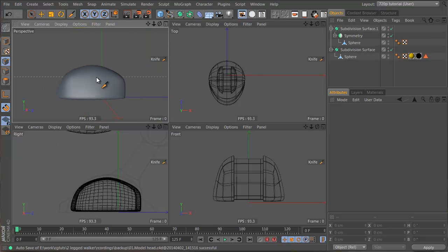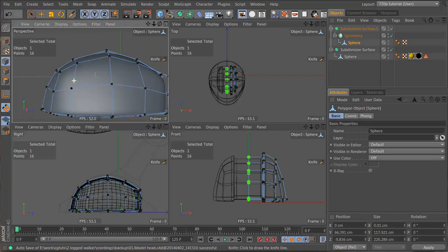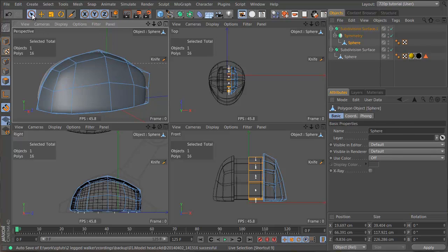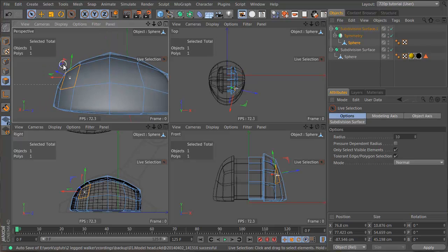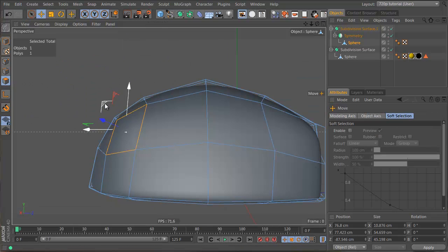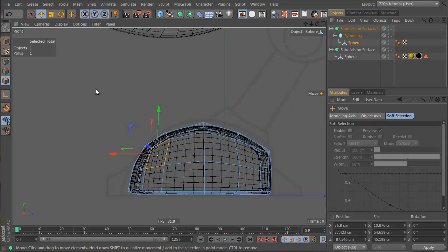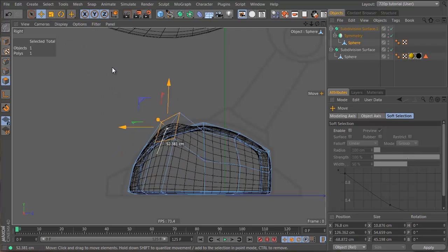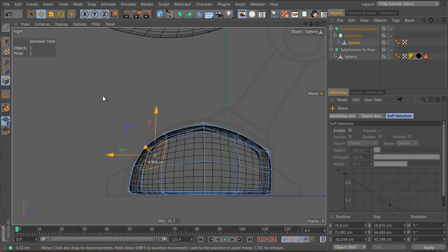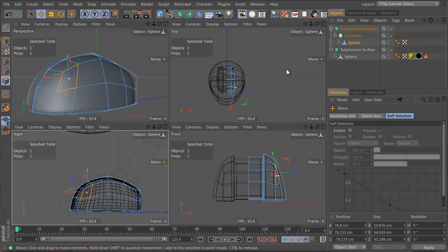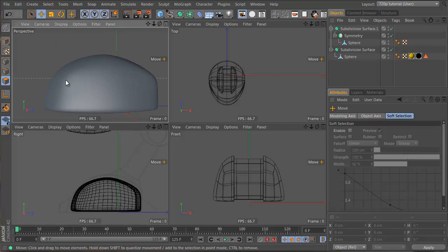So now everything we do on one side of the leg will be done on the other side. Now also, I don't like how this face here seems a bit sharp. Let's move this guy. It's in this view here. By the way, if you have any tools selected, if you click in the empty space in one of the side views, you will move only in that axis. So in the empty space, let's move him back a bit. There you go, that looks nicer.